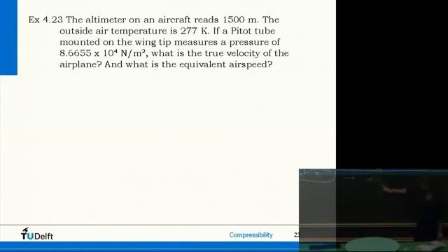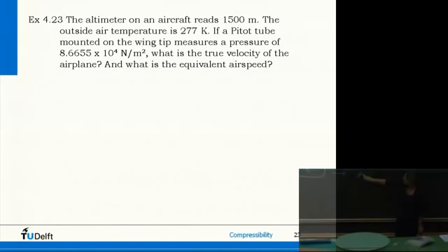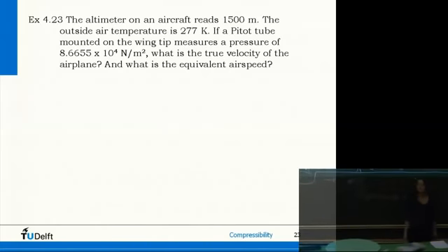The speed goes in, and then the tube fills itself with air. So what is the pressure that you measure here? Stagnation pressure, indeed, because it fills itself and then it doesn't flow through. So if you put this tube into the flow, this pitot tube measures the stagnation pressure, or total pressure, there where the speed is 0.